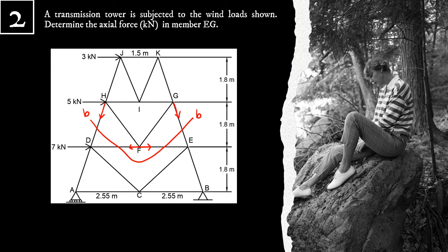Just like in the previous problem, we have 4 unknown forces. But if we take moment at point D, you will realize that DH, DF, and EF pass through point D. Therefore, they have 0 moment about point D. Only force EG has a moment about point D. Therefore, by summation moment at point D equal to 0 alone, we can already solve for force EG.